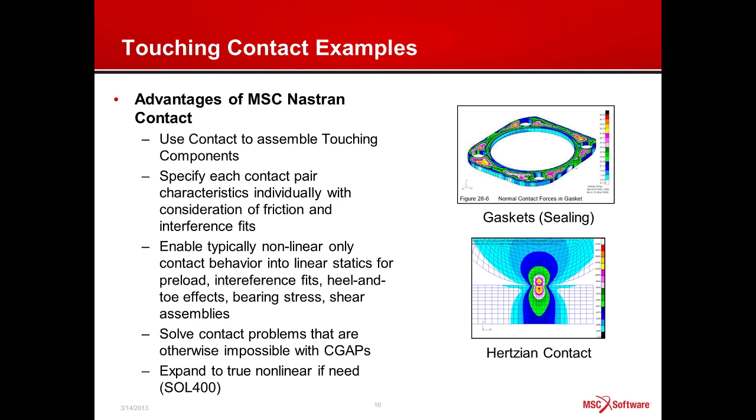It's very tricky to get to convergence, especially when things start to slide and move in all sorts of directions. So this enables general touching contact with very complicated geometry without having to define any surfaces or anything. The only thing you need to define as a user is to select the components, which we call contact bodies, and define which contact body sees which other contact bodies in your assemblies. Usually it's a handful of those to define. It takes only a few minutes.